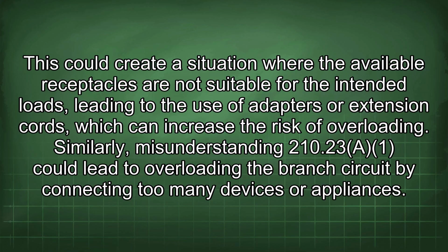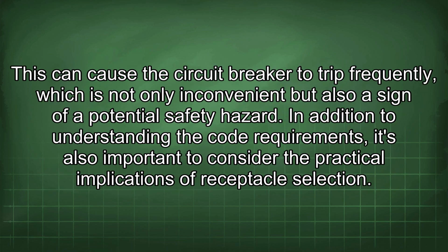Similarly, misunderstanding 210.23(A) could lead to overloading the branch circuit by connecting too many devices or appliances. This can cause the circuit breaker to trip frequently, which is not only inconvenient but also a sign of a potential safety hazard. In addition to understanding the code requirements, it's also important to consider the practical implications of receptacle